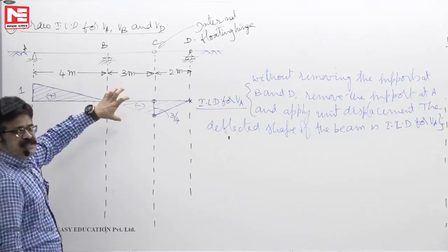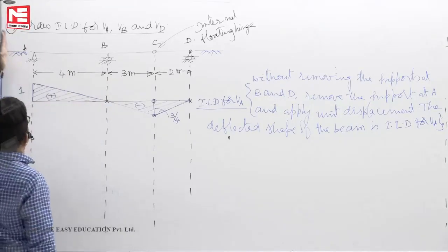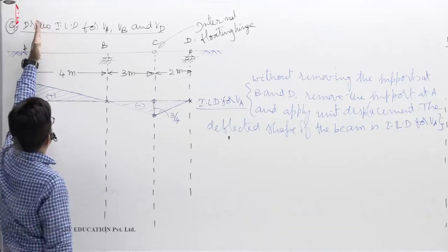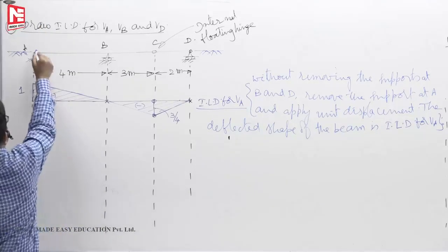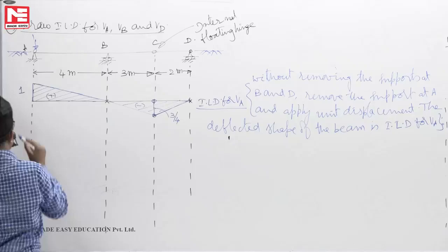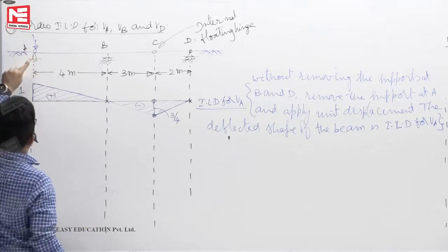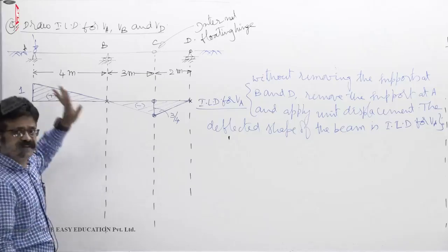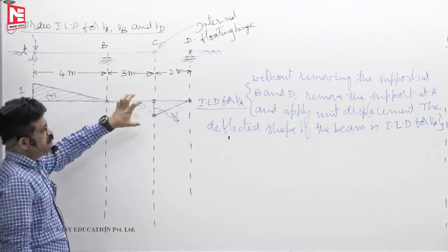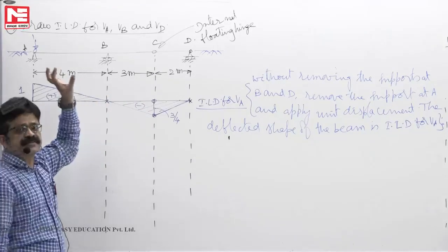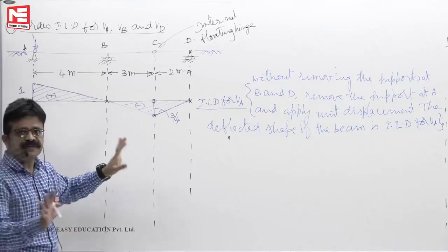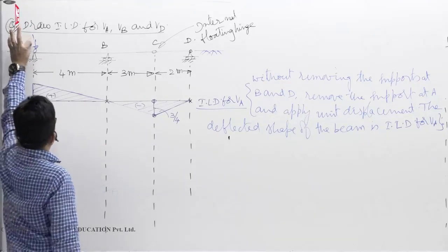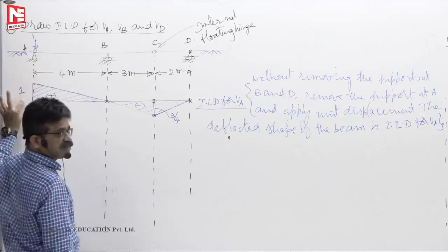What this diagram tells you, how to read this one, is when the unit load enters the bridge, the influence of unit load, that means when the load is here, the influence of unit load on VA is 100%. Because this entire diagram is for VA only. From this diagram, other than the reaction at A, no other information you can get.